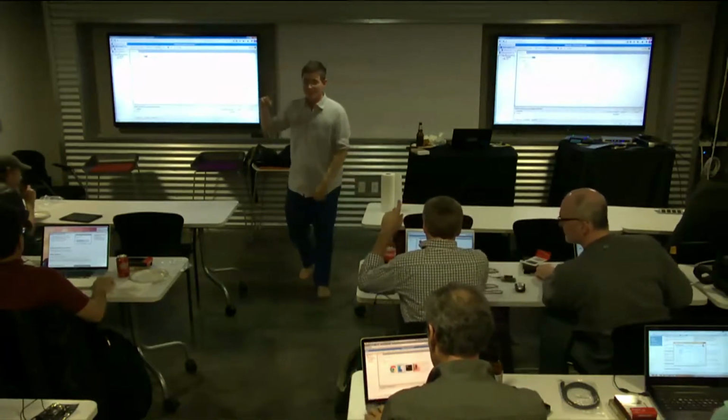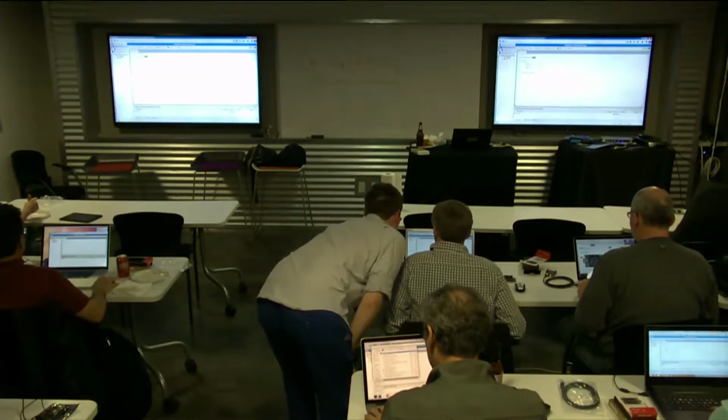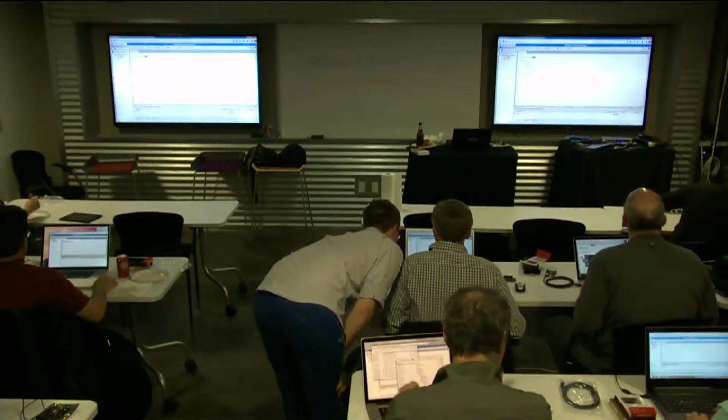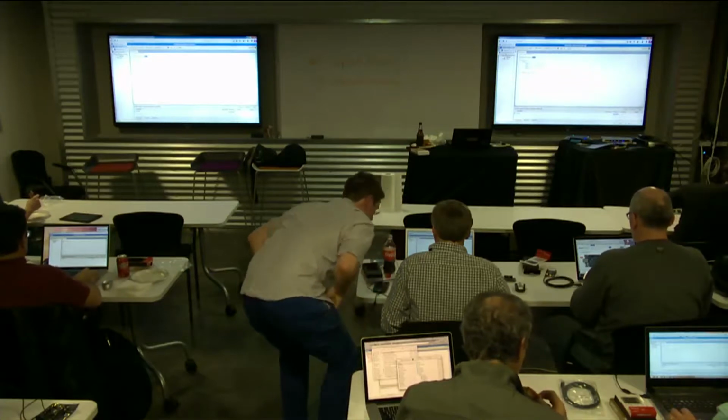Go to the main file. So here's your program. There's your main. This is what's executed. Right now you're going to blink the red light every 200 milliseconds. And if you wanted to change it and say blink the green LED, it's LED green.